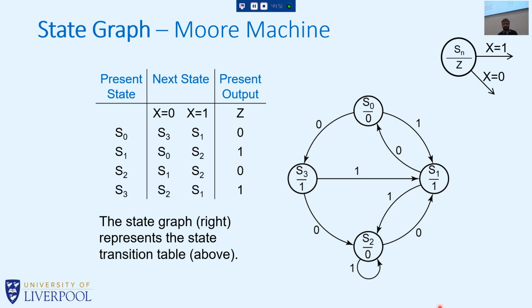Sometimes, if an input is a given value, like here, if we're in state 2 and the circuit input is 1, the test input to that circuit, it's just going to cause us to cycle around and go back to that same state. A bit like maybe those red traffic lights, maybe when the input is 0, let's say, the input being defined as there's no car being detected and no one's pressed the button on the traffic light, then its default is maybe to remain in a green state and just continue cycling back round, okay?